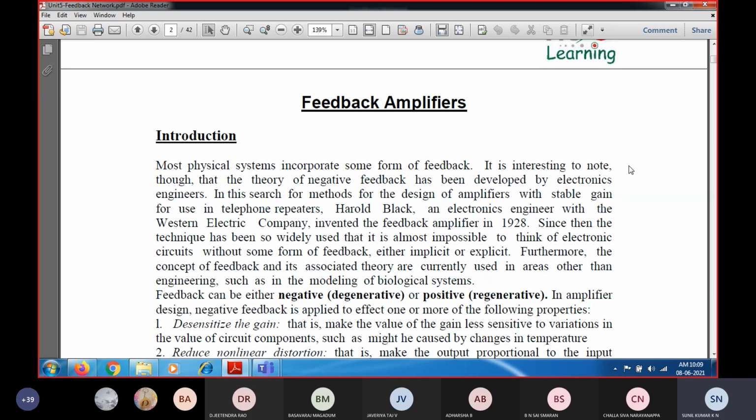that is, a common source amplifier along with the source follower. This is also called a common drain configuration. So having understood the configuration as well as the frequency response, how it is going to vary with respect to the frequencies, we have developed a high frequency equivalent model. It is also called a hybrid pi model. So that is the high frequency model we have developed, and we have seen what are the causes for the high frequency model.